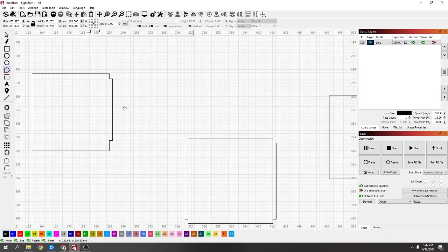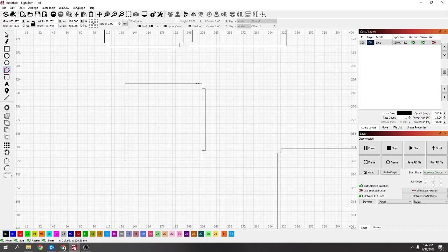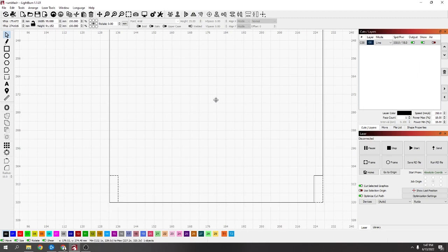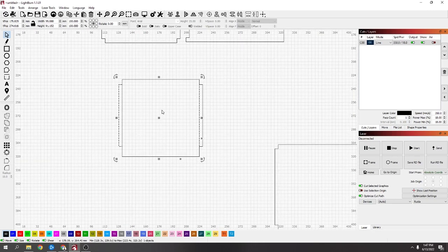One other way you can do it as well, actually. If I wanted this sticking out both sides, you could do it the same as I originally did it, but here is another way that might help someone in the future. You can click on it, press Ctrl and D and duplicate it, and then come up to this mirror tool and mirror it, zoom in and hold shift and drag this till these two lines line up over here, and now you've got the same overhang here.